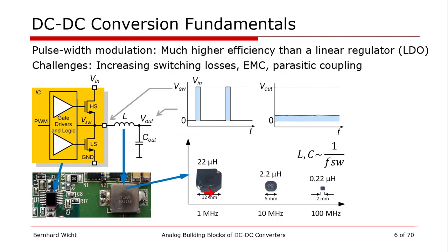The idea to bring these components down is to simply decrease the storing time, which means we switch at a faster frequency. As we can see here, the higher the frequency gets, the smaller our components get. We eventually get the chance to go for a package level co-integration of these passives, or even integrate those passives on chip.